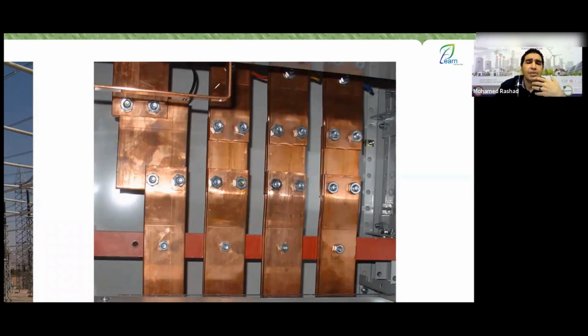But what I want to clarify for you here in this part is that when you come to tighten your bolts, you use a tool called a torque wrench. This wrench, engineer, is set to a specific torque, a certain Newton meter, based on the manufacturer's recommendation. The bus bar is tightened, and after it is tightened, you take a highlighter and start making a mark like this. This mark is drawn on the bolt itself.